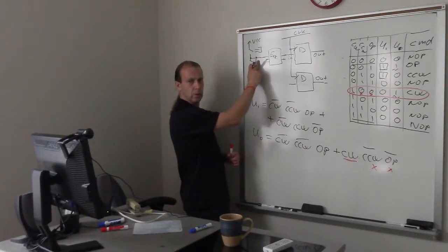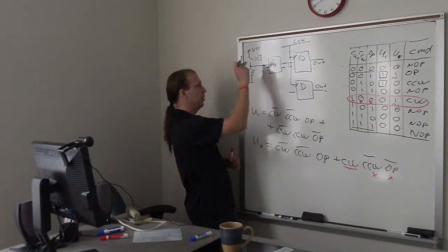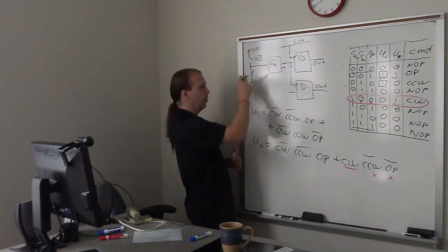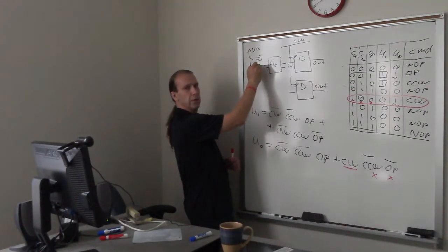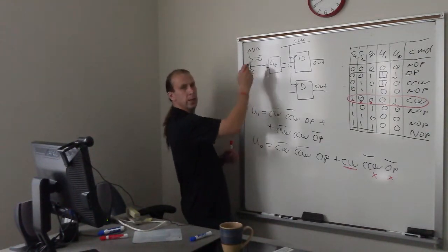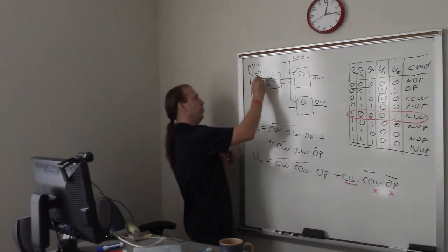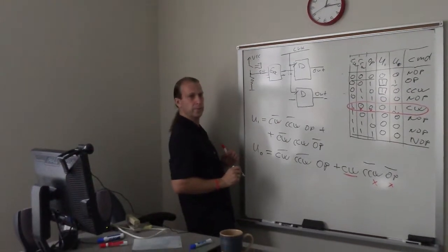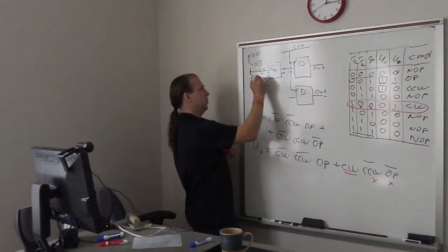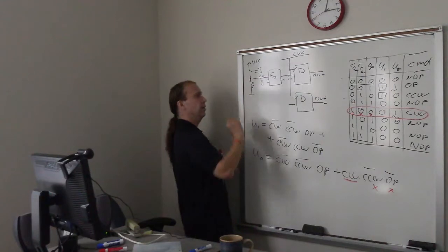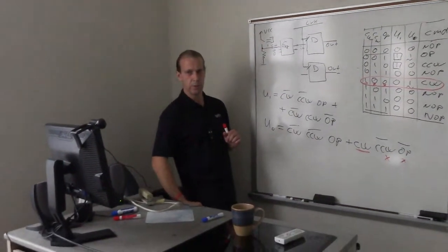those two signals, which are outputs of our encoder, will stay high as long as the push button is pressed. Right? So, in other words, we press the push button, we generate a high logic level here, and for example, this will be the high logic only on the clockwise, on the CW command. And let us say the other two will be zeros. So it will be a 1, 0, 0 combination.